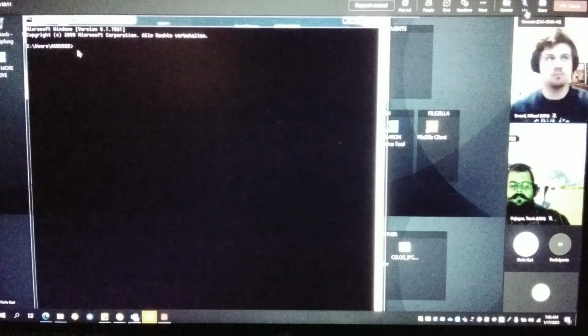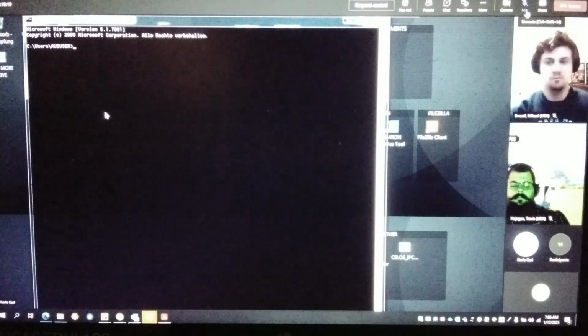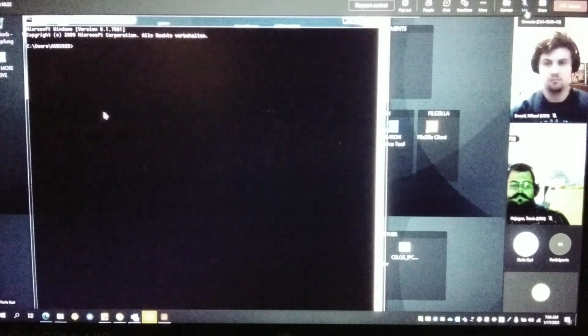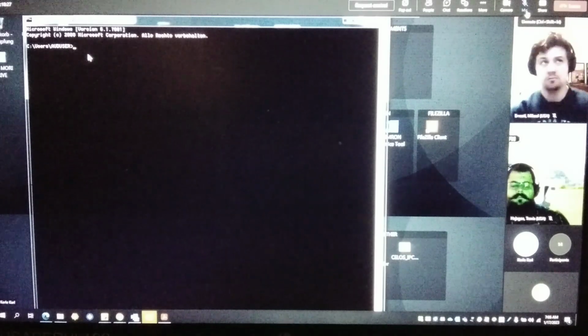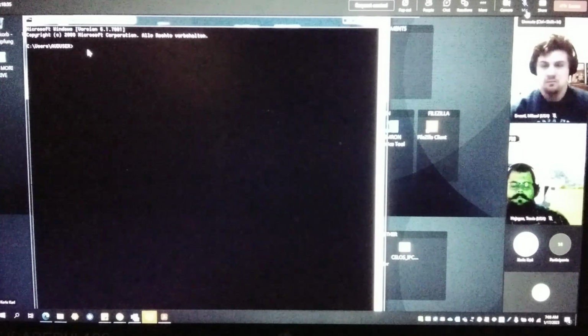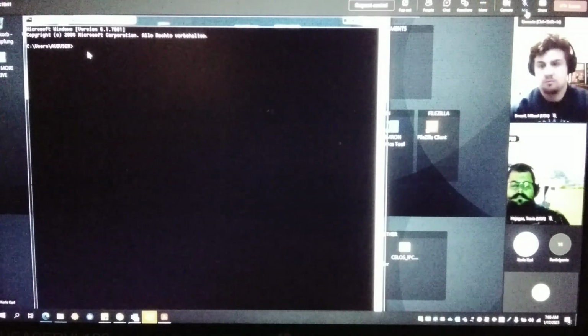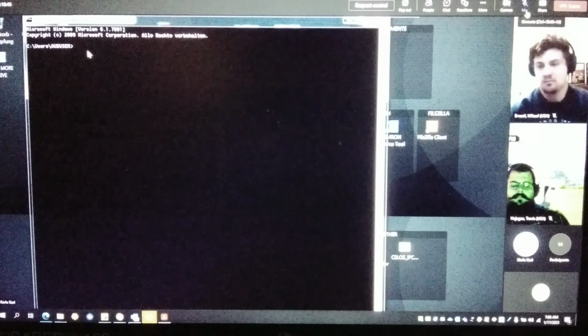And why do I use that? The reason is very simple. This here is accessing the lowest level of the TCP/IP protocol connection. And when I get the right indication here, then I know what is really used by the communication processor. And if this IP address indicated here is identical with the one inserted shortly before, then I know it will match, okay? That's true, okay? So far so good?